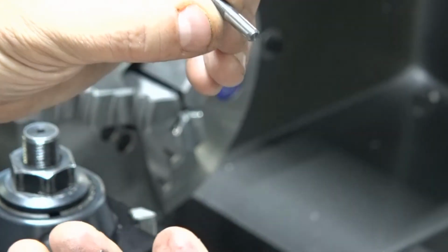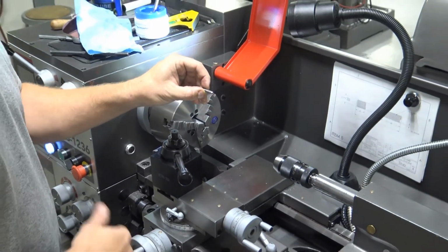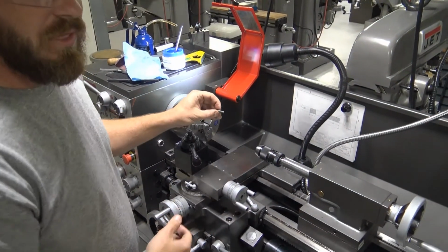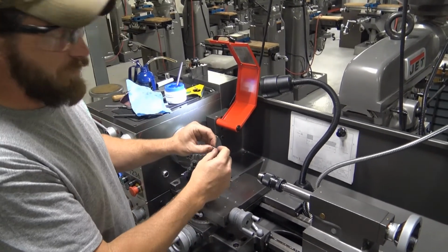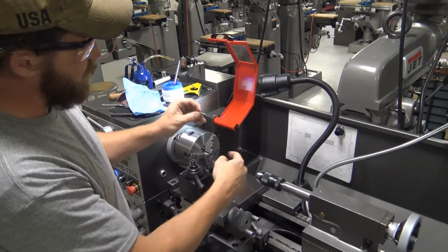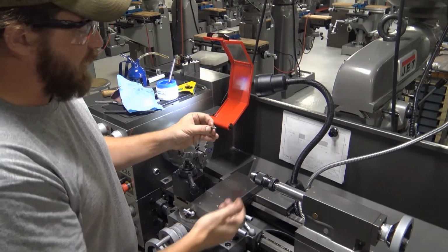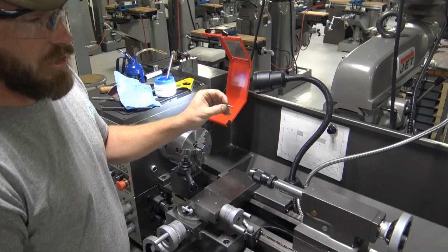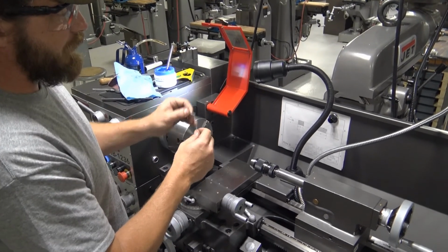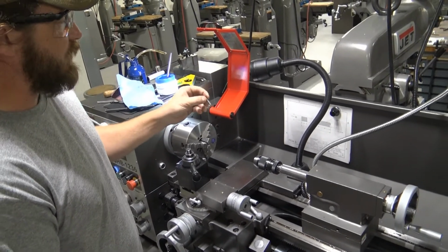Now all I'll have to do is put this back in and do the same on the other side. Obviously a 1/4 inch length, so how many revolutions of the die would that be? It would be 8, because 1/4 of 32 is 8. So I would do 8 full revolutions. It's the same thing, but instead of going 16 turns, I'm doing 8, and then we'll put that portion on that end of the shaft. Once you do that, that part will be done. So that will be one of the parts that you have to do for lab 5.